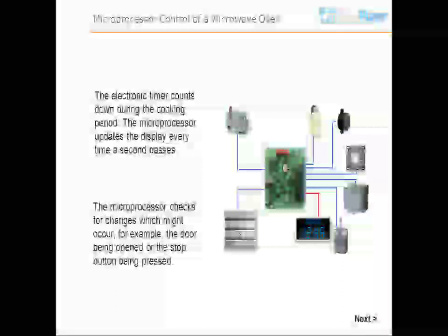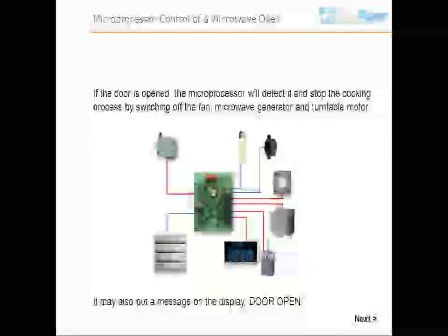If the door is opened, the microprocessor will detect it and stop the cooking process by switching off the fan, microwave generator and turntable motor. It may also put a message on the display, door open.